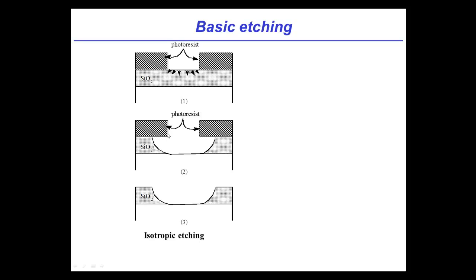Sure. So usually you remove photoresist with solvents. You could put them in acetone, and acetone will chop all this up and dilute it away. There are slightly stronger ones used in the semiconductor fab industry that have other advantages, but that's generally what you do. It's also common to remove it in a plasma. The photoresist is a polymer, so an oxygen plasma will eat it up. It burns it. And the most common way to remove it in the semiconductor industry, because it leaves very clean surfaces, is to use something called piranha.